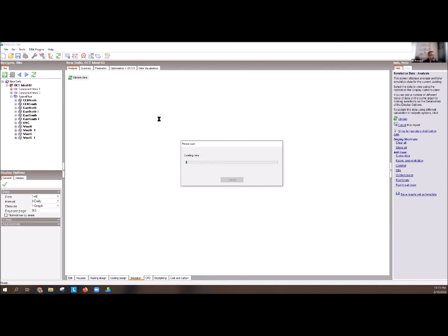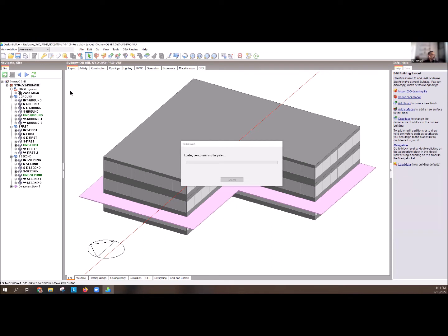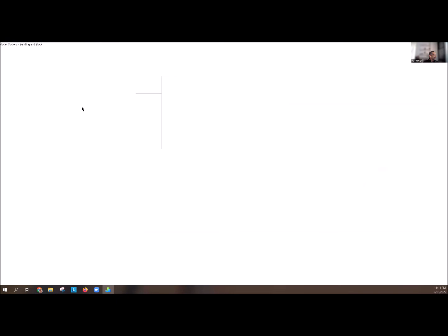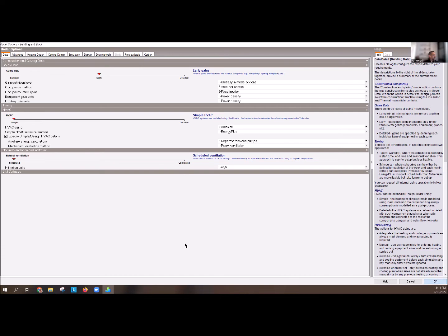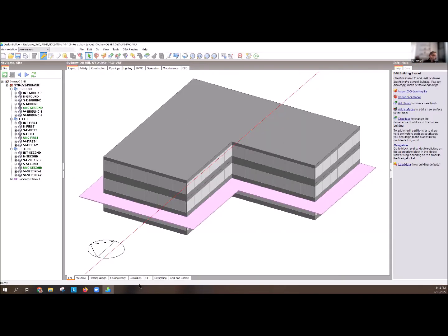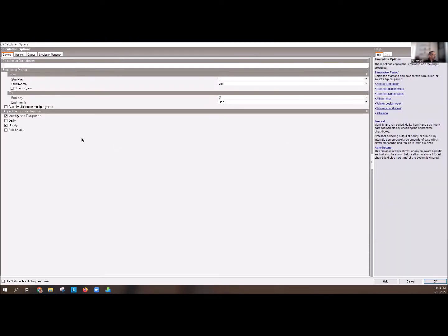But essentially then what you can do is you can run an energy simulation, you can run a peak cooling load simulation. All of those can be done in one or two runs. And then you can change your construction and redo that again. Then you can add shading devices and redo that again. So let me remove my air conditioning system. So no detailed air conditioning, just a simple one. And first, let's make sure that it runs.